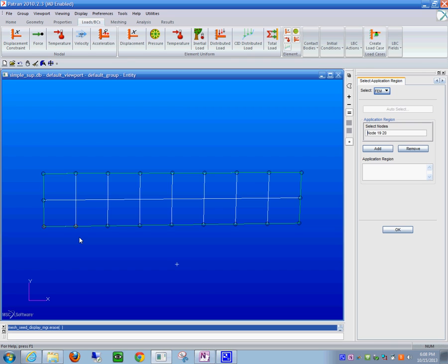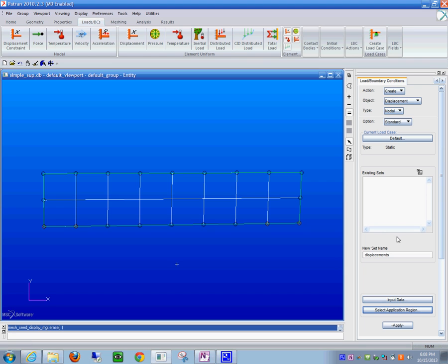See, select the nodes. And then maybe I'm just going to add to these ones and select this too. Yeah. So if you click on add, we have those 4, and click on OK. And then I click on apply. It should do my boundary conditions. You see what I mean?